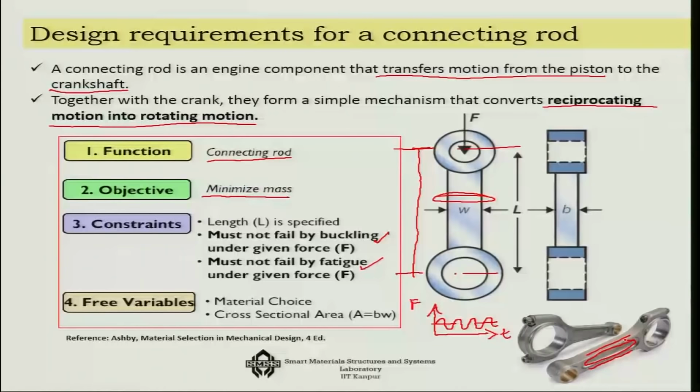So, I will not talk about it today, but the resonating frequency is also of concern, and hence if you reduce the mass, the natural frequency of the system, which is square root of k by m, goes up as you reduce the mass, the omega goes up. So, this fellow would not resonate. That is one of the strategies that they take.